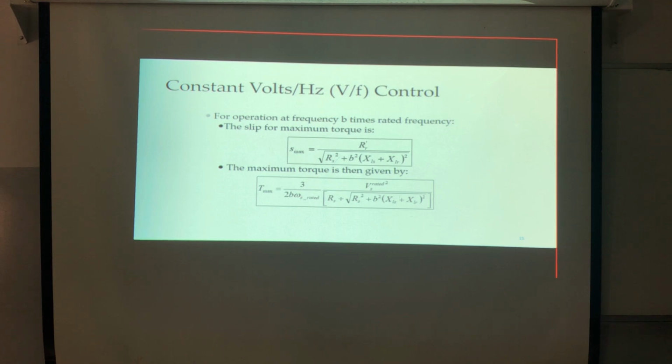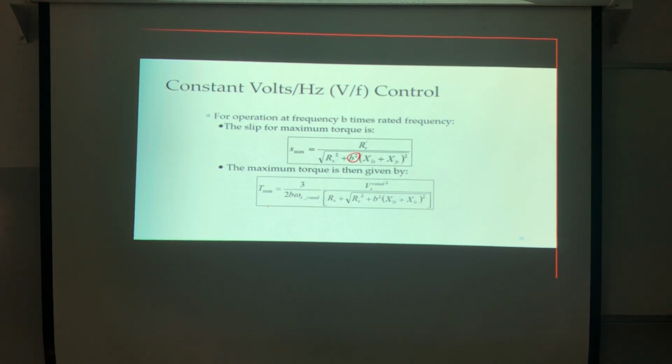Now, what will happen to the S max? S max will be reduced, correct? What will happen to the V max? It also will be reduced, correct? This is if I'm controlling the frequency above the rated frequency.